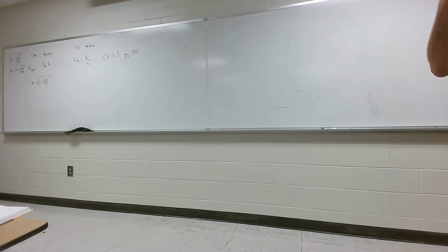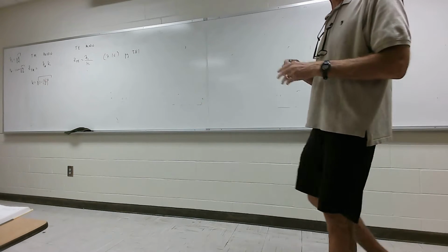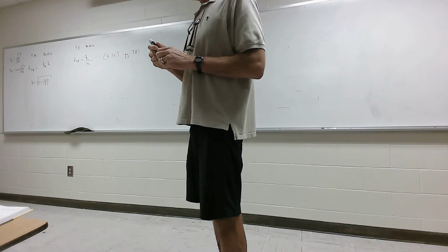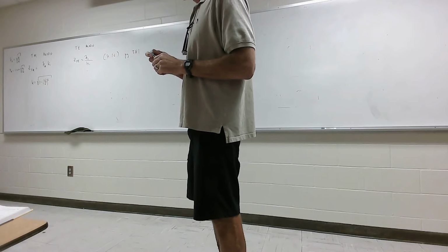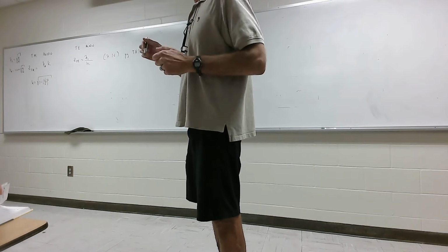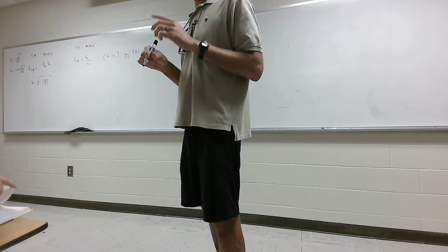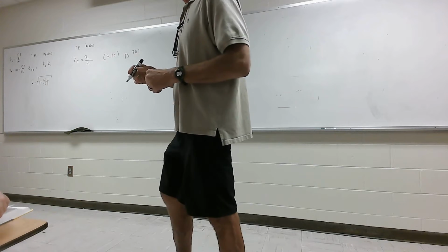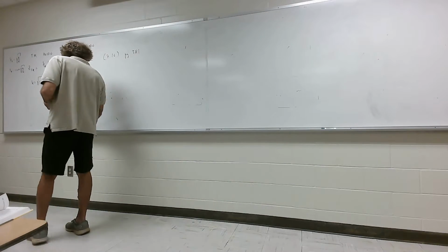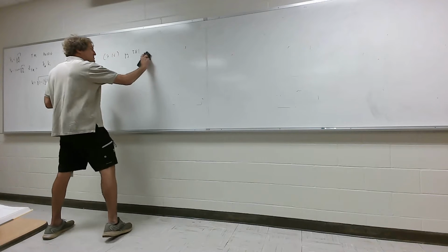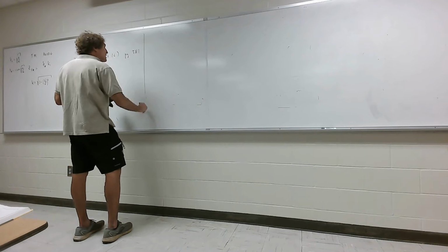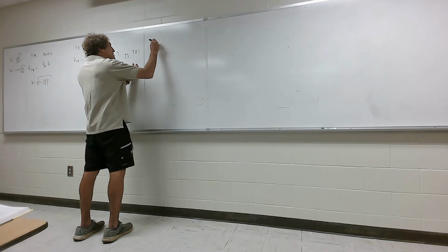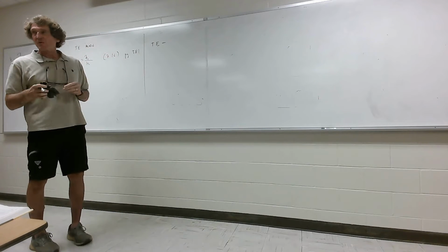Okay, now, the way I always start my classes, first, any questions about the homework or anything we've talked about up to this point? We basically went through the TM mode last time, right? And so now we're going to do the TE mode. Just get that down here. For the TE mode, the 1,0 TE mode is the dominant mode that the waveguide operates in. Let me go through it. I'll start right here. So, now when you have TE, that's the transverse electric mode.